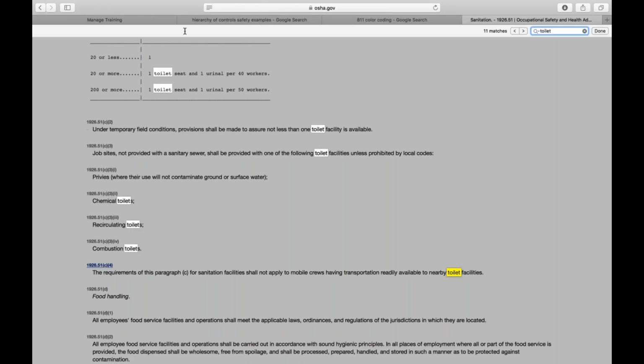So let me go ahead and move on now. You saw the personal health section, right? And then it talks about what methods we are going to use. Do we have potable and drinkable water, right? 6.21. Potable and drinkable water, and then what methods are we going to use to protect wall and floor openings as well? Are we using guardrails, floor covers, items like that? Okay, lifelines, cable systems or stanchions. And then I'm at 6.22.